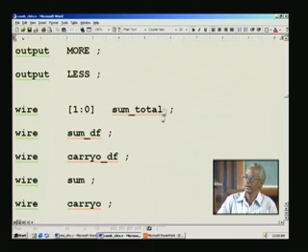See here we have used assign statements earlier and assigned some outputs. So whatever output appears in assign statements, they will be wire as such. What is a wire? For example, you have a combinational circuit, the output of which can be declared as a wire.